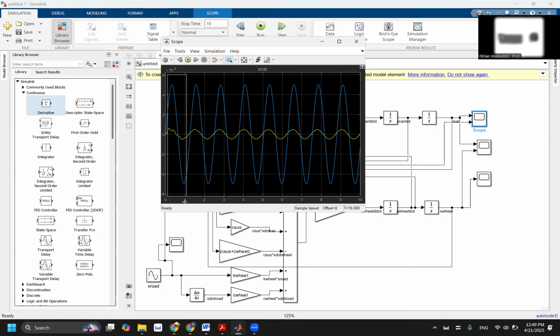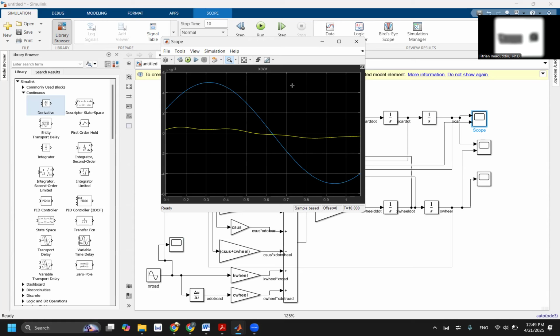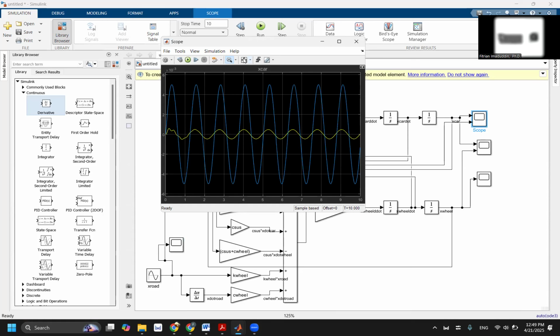So here, done. After that it is just the steady state response. All of it is steady state response. Even though you're actually operating in resonance, because you have a significant amount of damping, you will not go to infinity. Instead, the response will be limited, and what you're going to have is just the excitation. Okay, this is one of the simple examples.